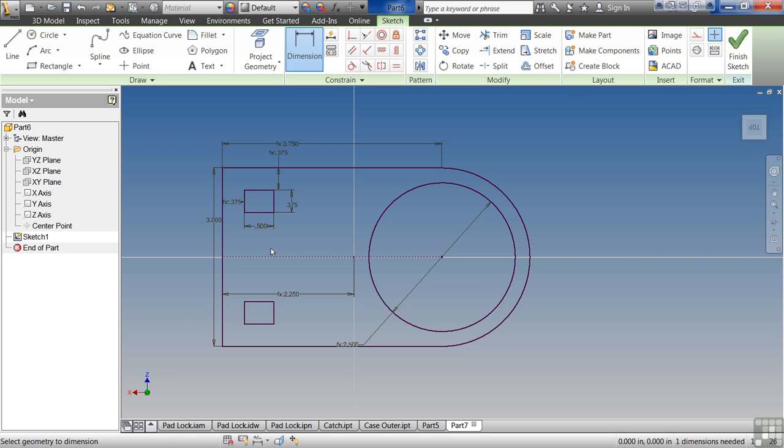Remember, capture it early, capture it as simple as possible, and you want to capture the constraints before you capture the dimensions. Basically, what shape should it be before what size should it be? And if you notice, the very last thing we do is the size. AutoCAD users, this is the opposite of what you're used to, and this is very hard for you to get used to. But sketch it out very roughly. Doesn't need to be pretty. It doesn't need to be nearly the right size. Create the shape you want by using the dimensional constraints, perpendicular, parallel, tangent, symmetrical, and then add your dimensions and define the size of it. Very easy to capture design intent, and it's a very powerful tool. So try to make your parts as smart as you possibly can.